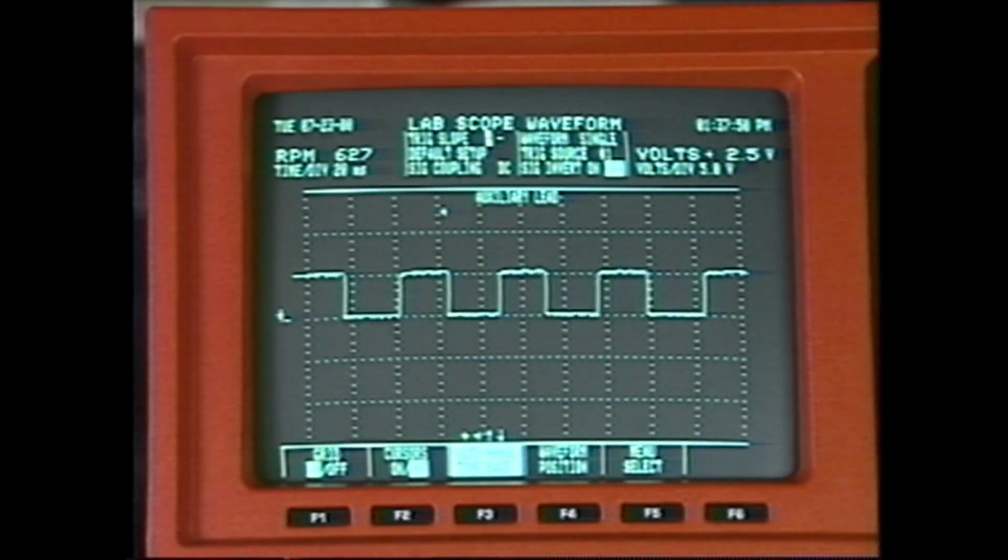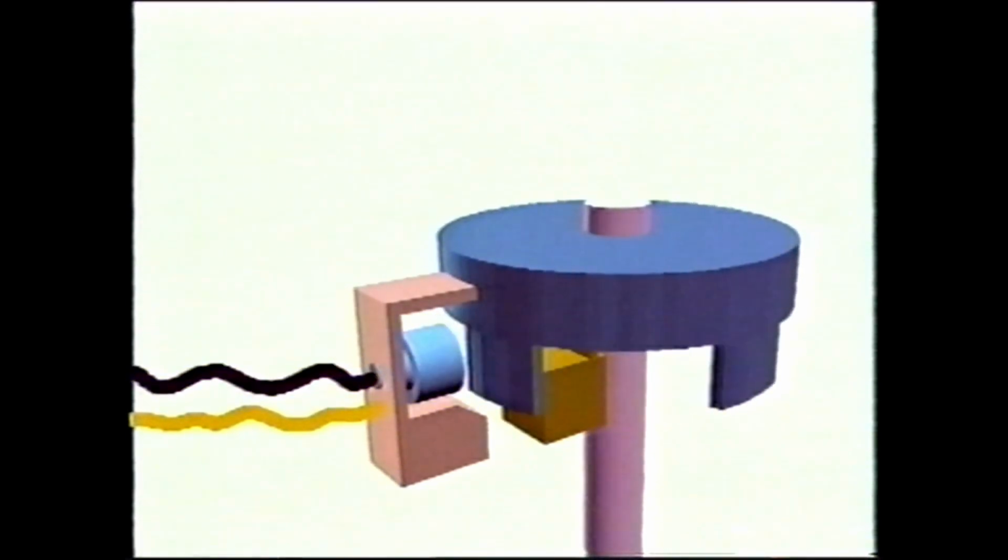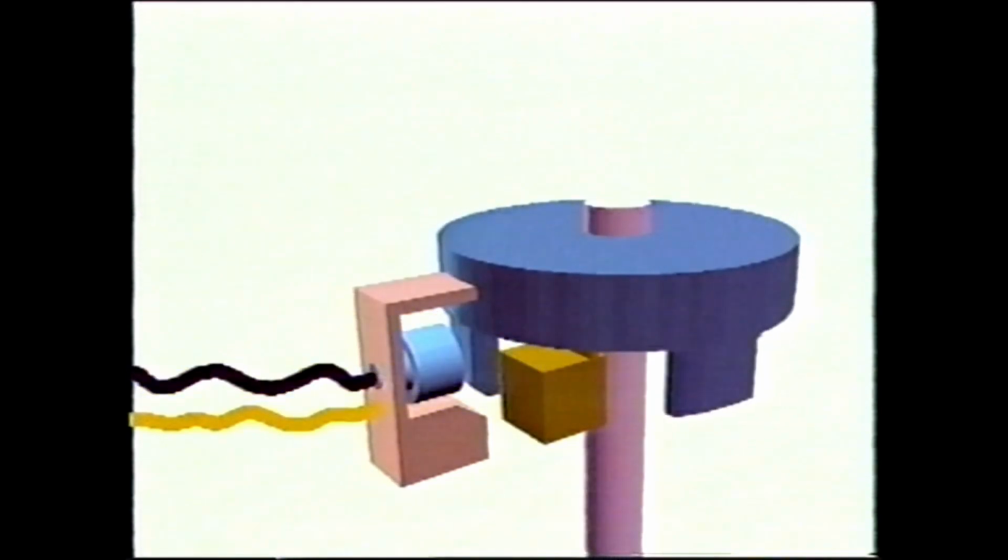The Hall effect switch generates a square digital voltage signal as a small amount of voltage passes through a semiconductor material at a right angle to a magnetic field. The switch has a permanent magnet and transistorized pickup assembly mounted near a rotating wheel with shutter blades. The magnetic field induces voltage in the pickup assembly and turns the switch on.